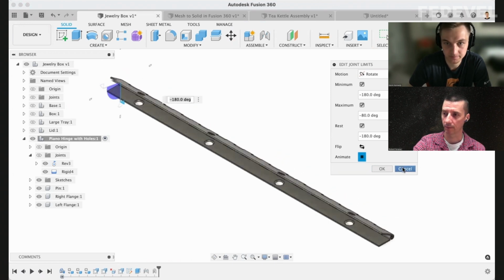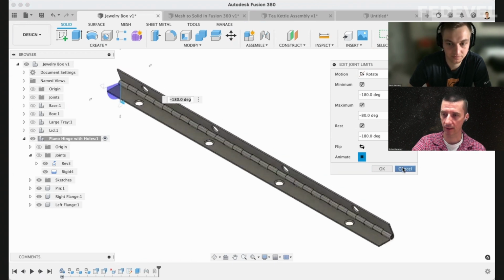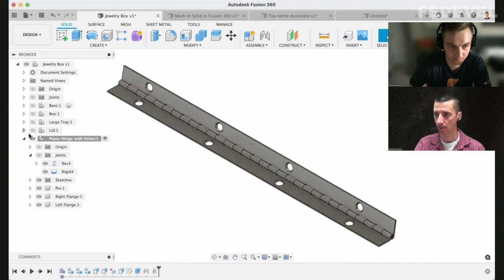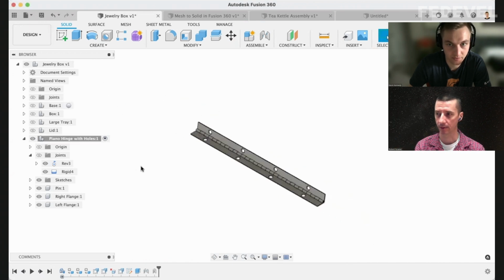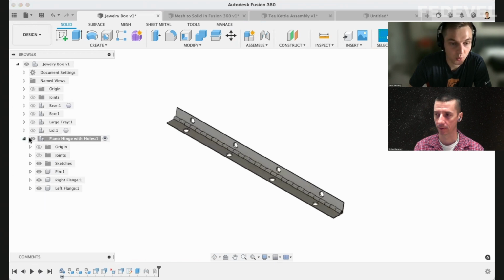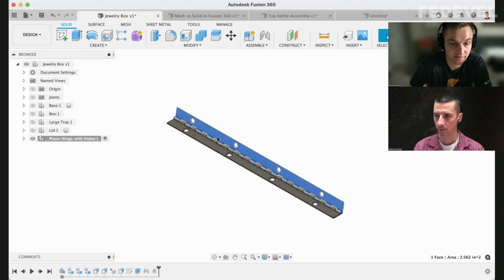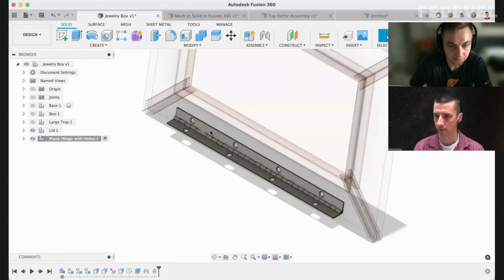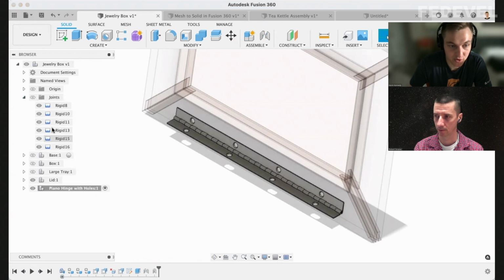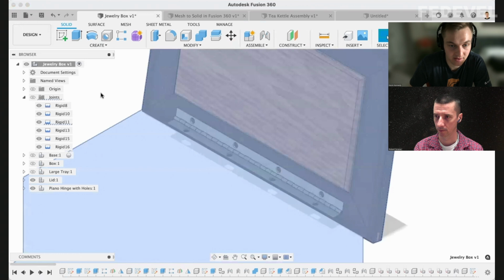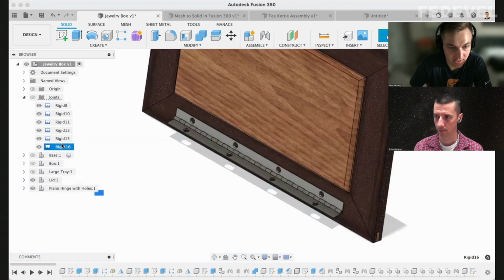And the other part of the lid, you just connect to this wing, and it will move together with the wing. Yep, that's correct. So when you think of joints, you want to go one by one and consider how that part would actually be assembled in real life. In this case, the lid would be screwed in here to this flange of the hinge here. And if I look at this top level joint folder, because I applied this to the parent assembly, you will see one of these in here.